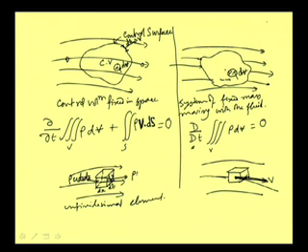So, this rho u is definitely here, then plus if there is a rate of change of mass flow in this direction with respect to x, that means if we write del rho u by del x, then after a distance dx, it will have a total change of this mass.